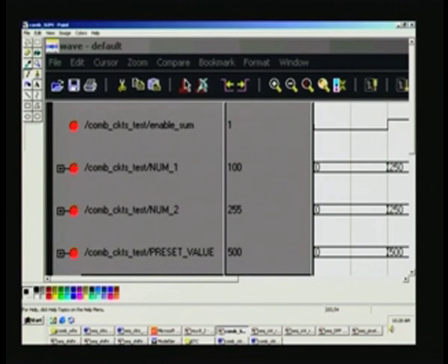And we have also seen how to use transitions of waveforms, whatever you had marked or highlighted, by merely pressing here, and along with shift, if you press here, all this will be highlighted. So whichever signal you want to highlight, you can use that one. In addition, for an additional signal you want to highlight, you can use control and press at the desired point. So once again, if you press control on an already highlighted signal, that signal will be deselected. It's very easy. It's the same as any Windows platform.